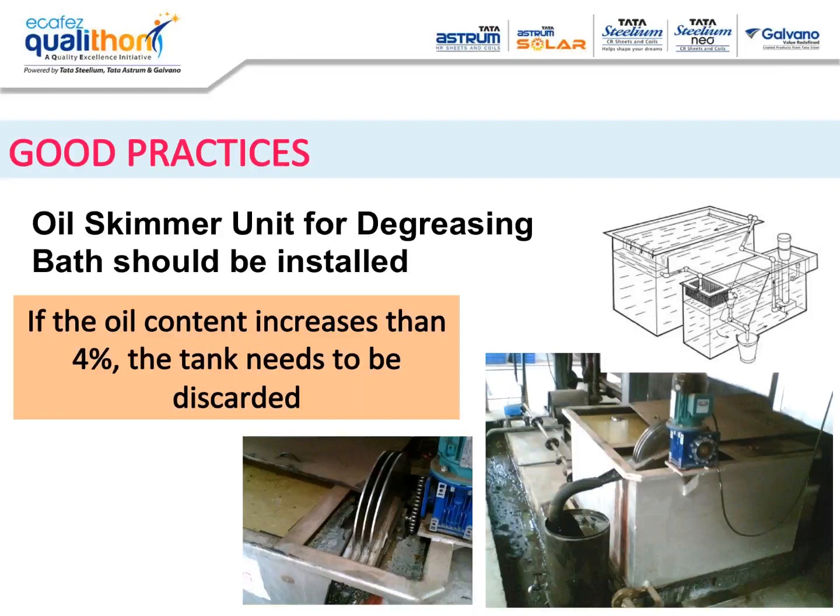Here what happens is whatever oil which is available, which is floating, will go into the drain or a gutter which is built into the tank, and only that water we will take out and treat it for water skimming. Okay, and we can skim off the oil and again that clean water or clean chemical can be taken back. Now two photographs of installation of a similar thing you can also see here at the bottom.